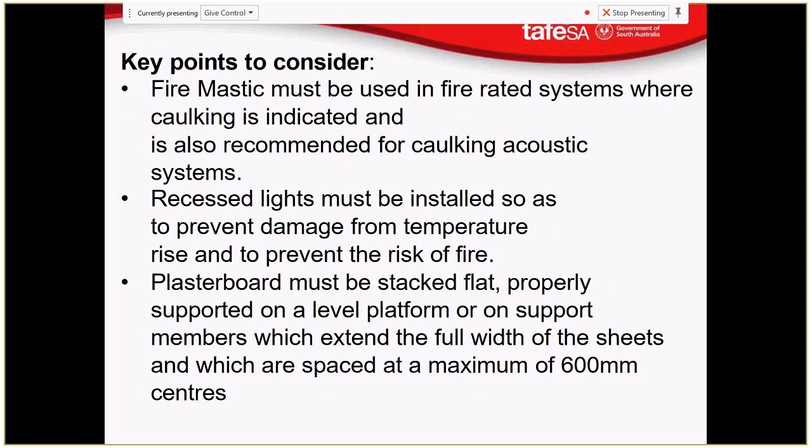Back to fire ratings again. Key points to consider: fire mastic must be used in fire rated systems where caulking is indicated, and is also recommended for caulking acoustic systems. I think it's very much a no-brainer. Recessed lights must be installed so as to prevent damage from temperature rise and to prevent the risk of fire. So they have to be installed as per the manufacturer's specifications.